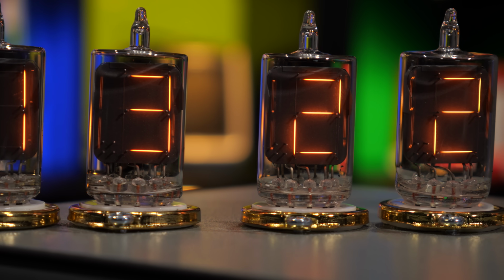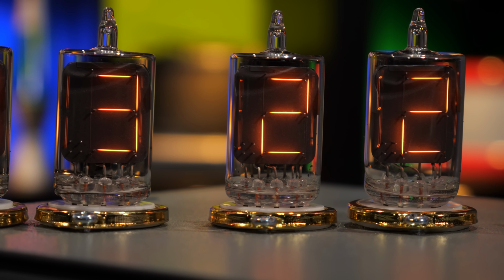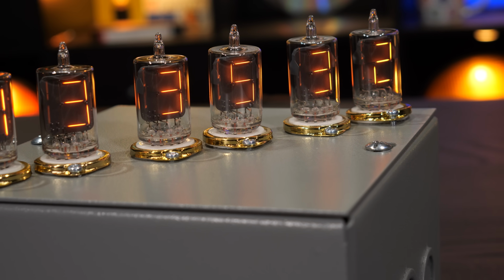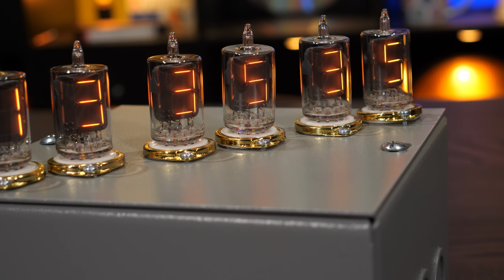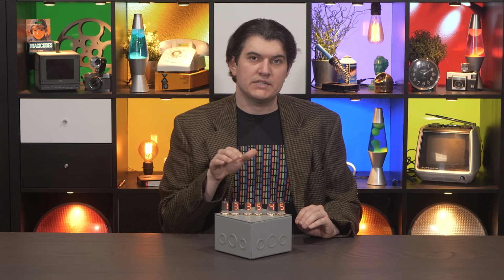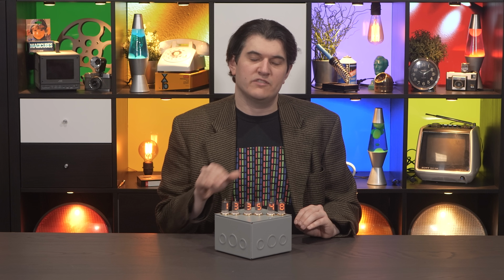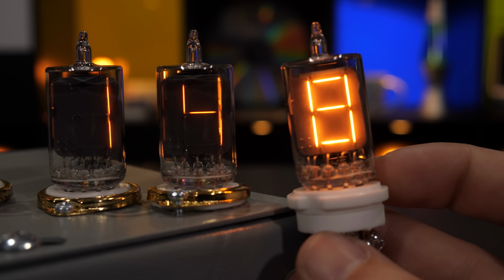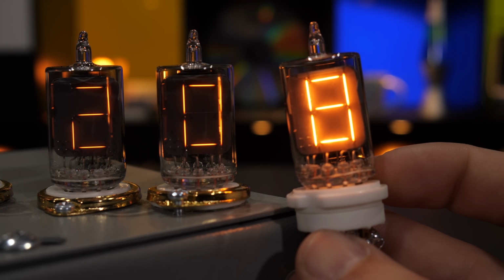RCA designed these to last 100,000 hours, and well, that's only going to be possible if the filaments burn quite dimly. So they're not producing much light towards the blue end of the spectrum, and a blue filter will really cut their output. Now, to be fair, the tubes can be a lot brighter than they appear in this clock. They're power limited here thanks to the BCD decoder chips I had, which are not capable of passing 25 milliamps. If I apply 5 volts directly to a tube, we can see that it can get this bright, which is honestly impressive. That's definitely brighter than a Nixie tube, and whiter than I was expecting.